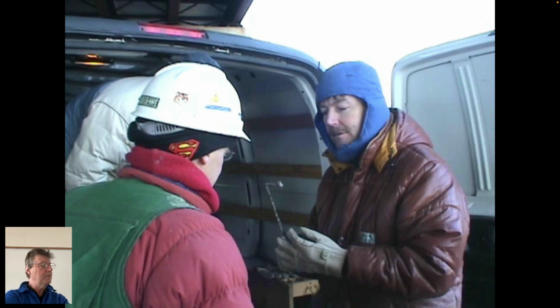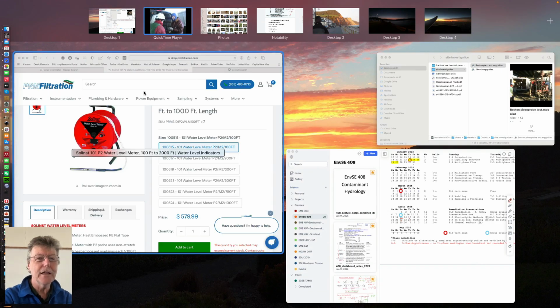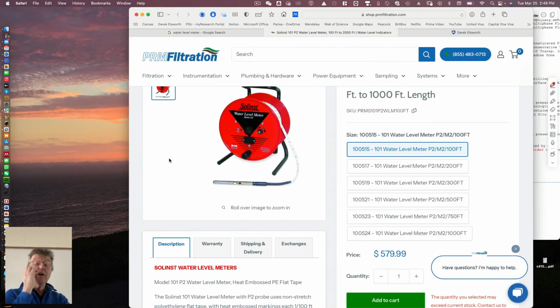Good. So we've talked about 2 out of 3 things we want to talk about. So the first was how to drill holes in soil and rock, and the different methods. How to get the best bang for buck from those holes by sampling from them and also instrumenting them once you have them there to be able to get the best value. And the third will be, now that we know what might be in place along a very thin sliver, which is the trajectory of the borehole, but probably only a few inches either side of it if we have samples, how do you get to see the picture of the whole site, which might have 10 boreholes that are separated by tens or 100 meters? How do you fill in across the site?